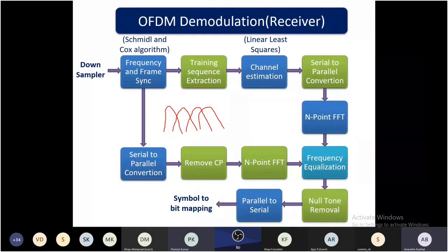This happens because whenever we are working with a USRP, there might be a chance that the local oscillator inside the USRP, if we fix it for 1 gigahertz, will give out 1.1 gigahertz instead of 1. This 0.1 gigahertz difference will impact OFDM more because all the subcarriers are tightly packed.